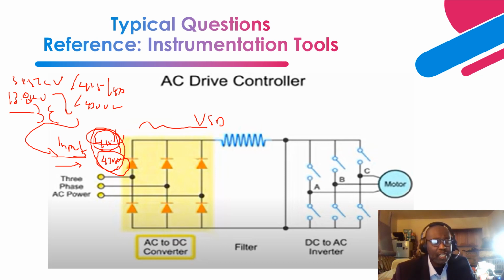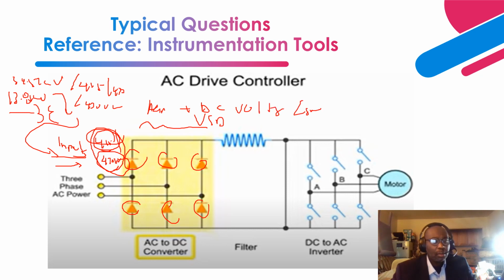Okay, so this comes in here, and these are diodes, right? Basically that rectifies the AC voltage input to a DC voltage equivalent. So after this side, you have a DC voltage with half cycle pulses in the positive, right? But it has some ripples on it, right?